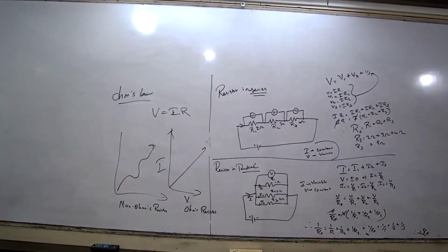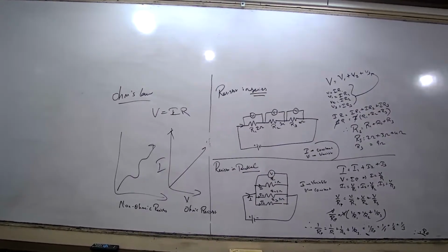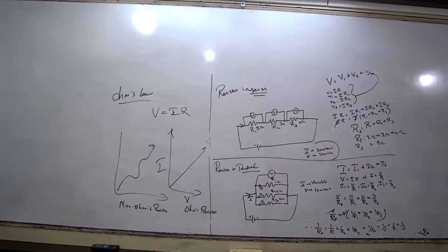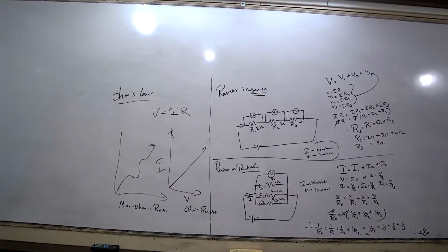Another concept we want to see is the heating effect of the current. I already told you, when more current passes, more heat is generated. It's due to the flow of electrons, and it can damage that circuit. Power is equal to V into I, voltage into current. You can substitute any formula, voltage also. At last we will get I square R. Joule's law we can say as H equal to I square RT.